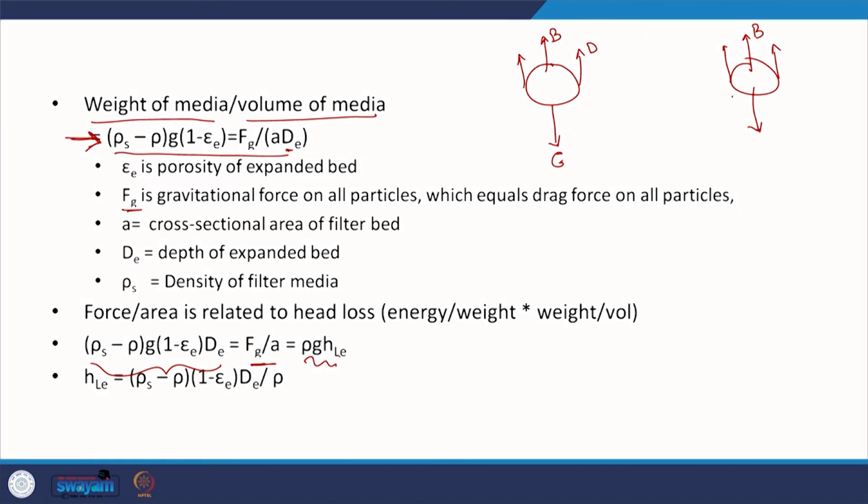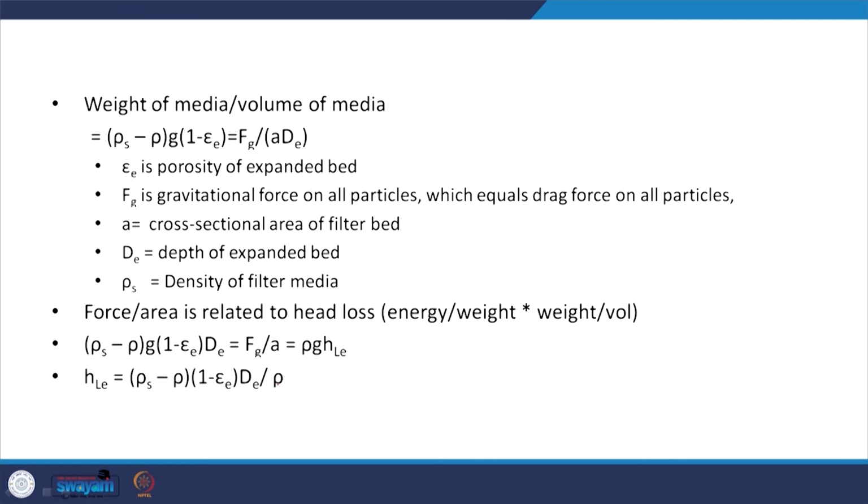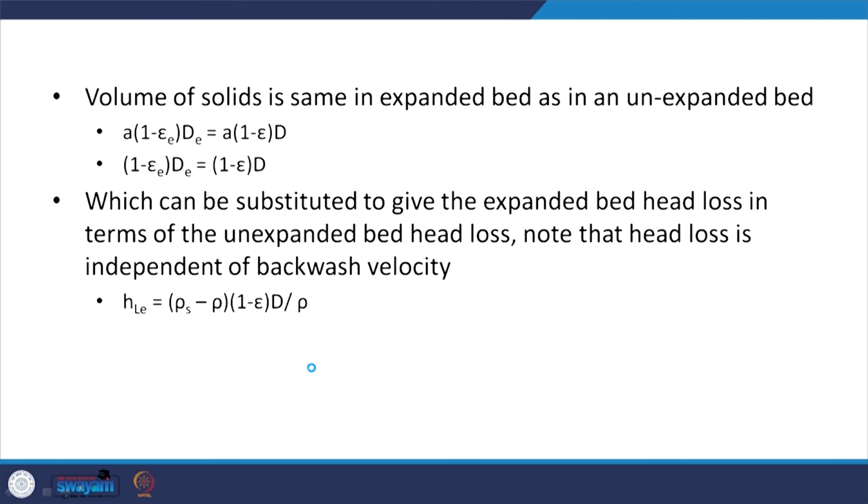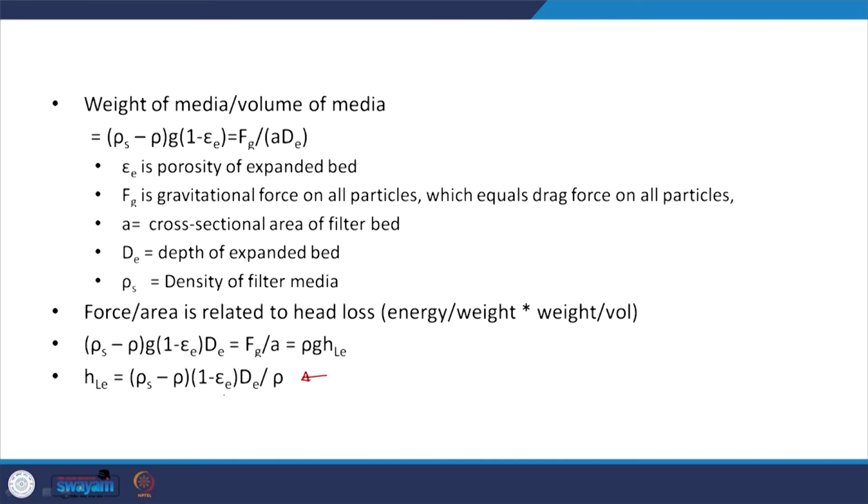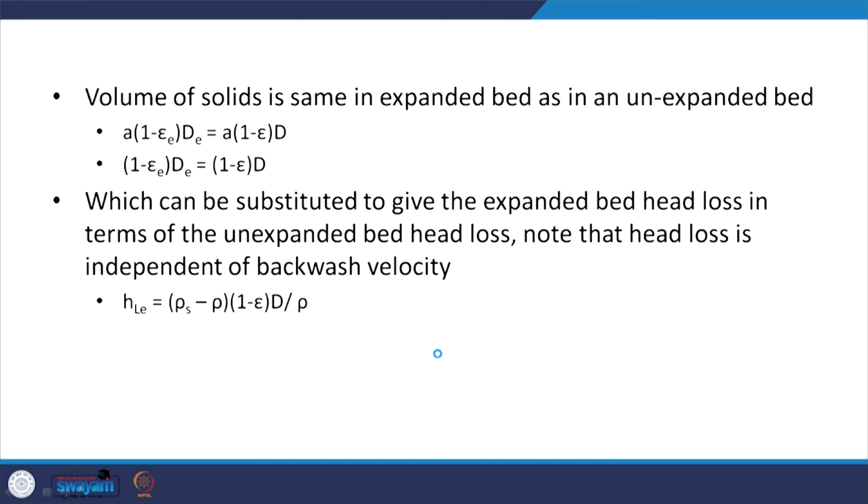Yes. So, from that I am getting the equation for the head loss during that particular backwash. Here obviously I have the porosity of the expanded bed, but I know how to replace that with the porosity of the bed in general. So, we have this equation, and I know that this particular set can be replaced by this. This is during the expanded bed when I am looking at backwash.